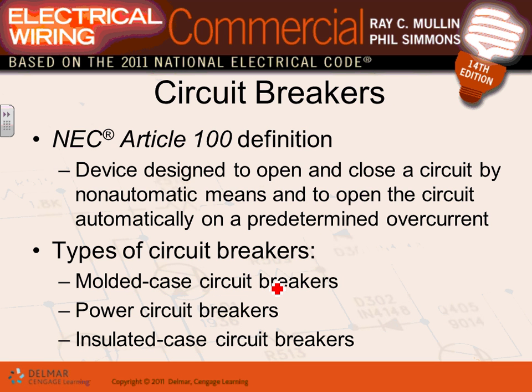Now, a few things about circuit breakers. I will go to the curves in a second. I have a couple of curves I want to show you. Definition of a circuit breaker, guys: a device that can be manually turned on and off and automatically opens if you have a short circuit or ground fault. That's it. You're looking at it right there. You can use it as a switch, turn it on and off manually, or if you have a short circuit, a ground fault condition, or an overload condition, it will automatically open.